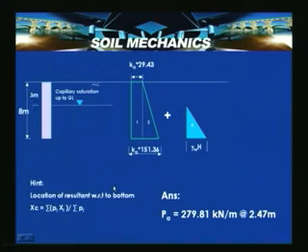So in this example, what we saw first is a case of dry soil, then a rising groundwater table, and then a soil subjected to capillary saturation. These conditions affect the active earth pressure and can induce lateral pressure on the wall. That is the reason why we generally use drainable or granular soils as backfill material. And in case you are prone to use low quality fills, then adequate measures have to be taken to drain the water behind the wall.